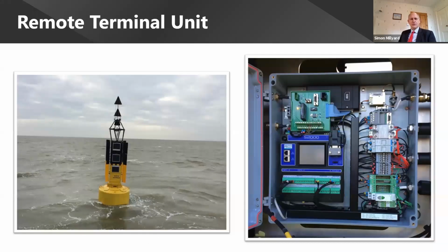Just for information, we spoke about the remote terminal unit. So here's a large navigation buoy, a Trinity House buoy. And in here is the control unit, which sits inside one of these, where it's got the name of the buoy there behind that panel. And the blue unit is the RTU, the remote terminal unit. It says S2000. And up here is the SIM card, which sends the data out on a mobile phone.